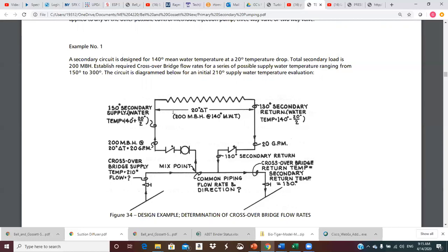The 500 comes from 60 minutes per hour times, I think it's 8.34 pounds mass per gallon. Well, as the water gets hotter, that 8.34 goes down because it's not quite as dense. And so Q equals 500 GPM delta T becomes less accurate as the temperature of the water goes up, but we still use it anyway. I just want you to realize that.